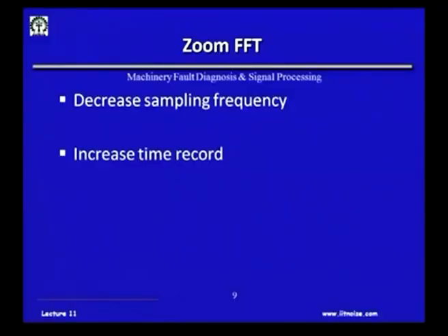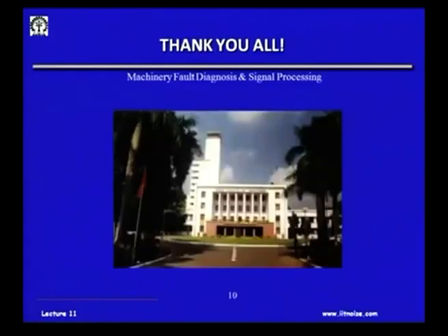And then another aspect of FFT is, I want to still with the available resources, I want to see much finer details, and that can be always increased, either you decrease the sampling frequency or increase the time record. Okay. So, sometimes decreasing sampling frequency may not be possible, then we have to increase the time record. Okay. Thank you.